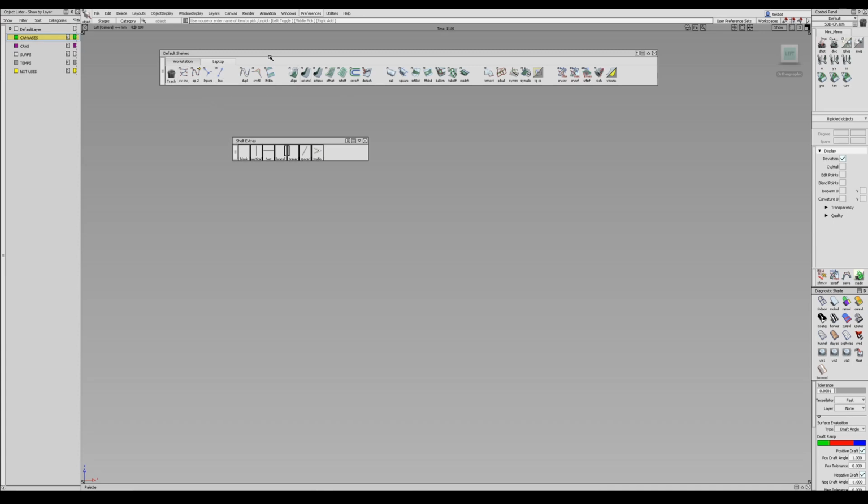So curves, curve editing tools, or custom curves. Some of the object edit features, surface creation, a lot of my technical surfacing or symmetrical tools, and then my analysis tools. Two of the other ones that I didn't mention in the curves are curve sectioning, the ability to trim curves with other curves, and transform curve, which is like a curve stretch. They're very similar, and allow you to stretch a curve, not just on scaling, but the overall shape of it.